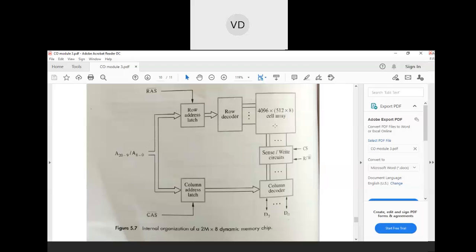By accessing that row. When you access a row, when you read that row, automatically the data will be restored, which means the capacitor will be charged. So when you are restoring the data, that particular row will be refreshed automatically. That particular row will be refreshed just when you read the data from it. When you are selecting the complete row, but you are reading only one group, the other 7 groups will not be read, is it not?